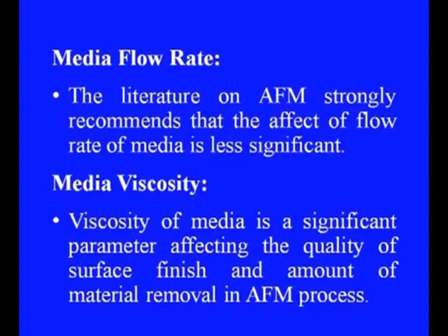Media flow rate. Literature on abrasive flow machining strongly suggests that the effect of flow rate of media is less significant. Then as far as the media viscosity is concerned, viscosity is a significant parameter affecting the quality of surface finish and amount of material removal in the abrasive flow machining process.